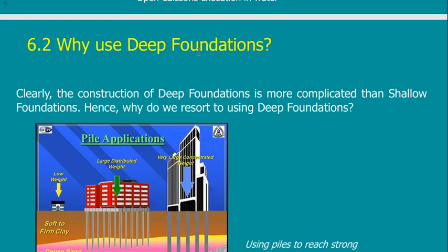Where to use the deep foundations and where to use the shallow foundations, we said it depends on the loading and it depends on the type of the soil. If I have very minor loading, very small loading with good soil or moderate soil, then shallow foundations are okay. If the load increases and the soil is still not very good, then in this case I may need piles to take the load from the upper layers to the stronger layers below.